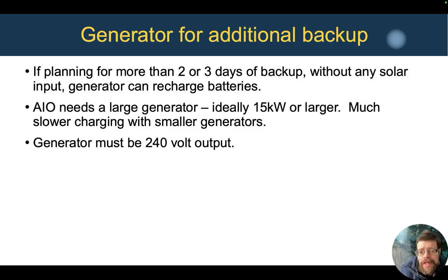So it can actually be a lot lower fuel usage, not to mention maintenance time on the generator, to run that generator for 2 or 3 hours a day at high load to recharge batteries and then run off the batteries in the inverter for the other 24 hours a day, rather than having that generator run for 24 hours a day, occasionally running a high load, but mostly running a much smaller load.